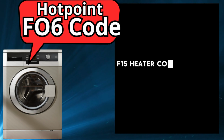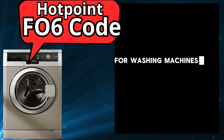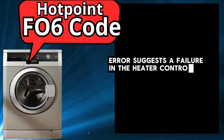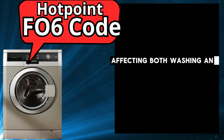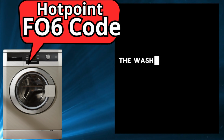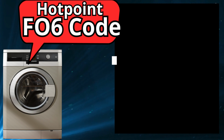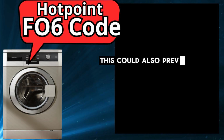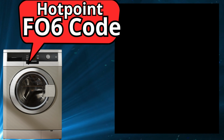F15, heater control fault. For washing machines and washer-dryers. This error suggests a failure in the heater control system, affecting both washing and drying functions. The washing machine may not heat water during the wash cycle, causing poor cleaning results, or it may pause mid-cycle. In washer-dryers, this could also prevent the dryer from working properly.